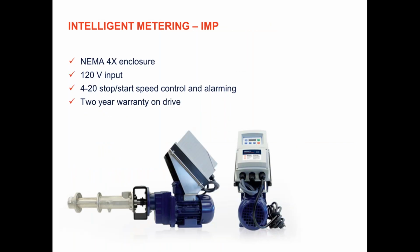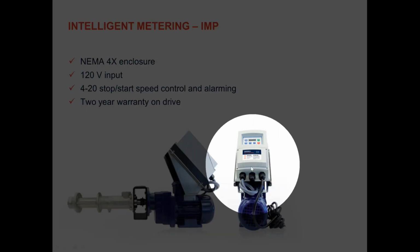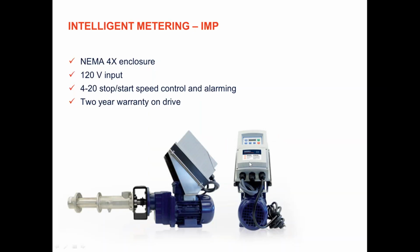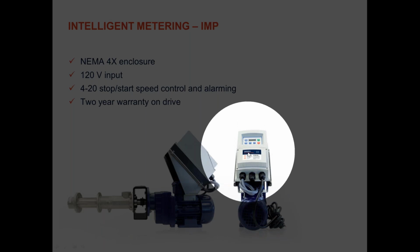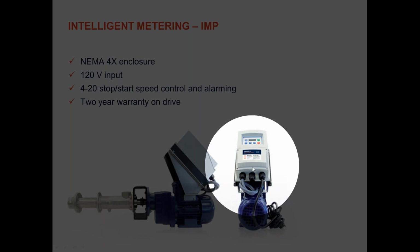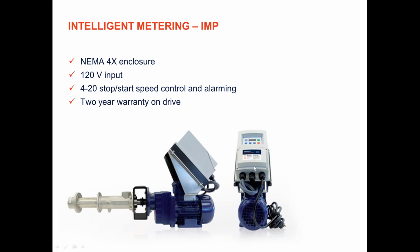If you want to make this pump intelligent, you can slap on a piggyback VFD that'll take a 4 to 20 signal. Seepex has standardized on this with our chemical metering pumps because this way it can be tied into a system, into SCADA, or be tied in to match and correlate directly to the speed of a centrifugal pump.